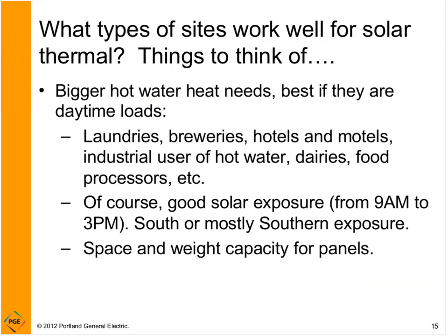Wanted to talk briefly about sites and what makes a good site. When you think about solar thermal, there are two things to consider when you look at your site. One is what your load is, or how much hot water you're going to need. In addition to how much, you need to think about when. So the when aspect of it will determine how much storage capacity you need for your hot water.